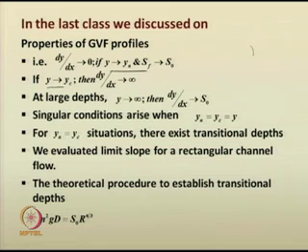You have also seen that at large depths, that is when y tends to infinity, the water surface slope is almost equal to the bed slope. You have also seen certain singular conditions arise. Singular conditions means when dy by dx is in the 0 by 0 form. A singular condition arises when the normal depth is the same as the critical depth, which is the same as the depth of flow.